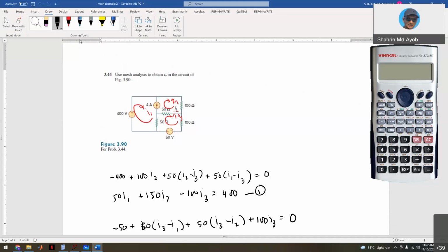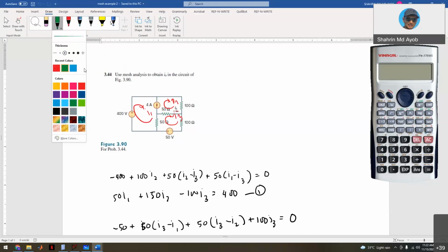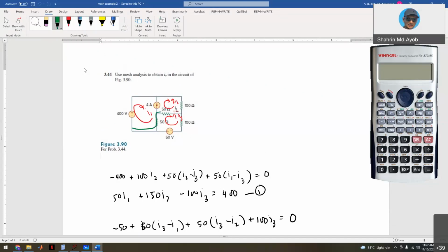So your mesh currents I1 and I2 are clockwise, and then you create a super mesh, also clockwise. Okay. Then I use the super mesh to calculate I naught, and the super mesh current direction is opposite to I naught. Oh, I see.